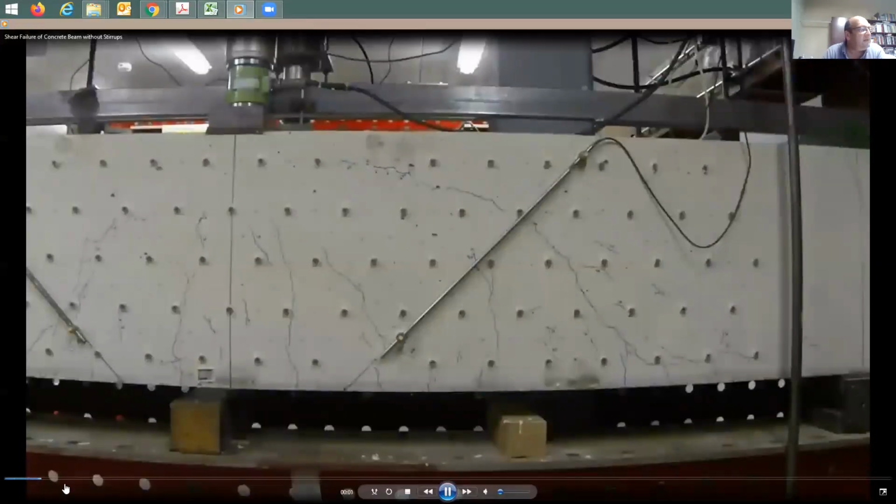Let me show this testing here. This is testing for shear. Now, in this case, the beam is very strong in moment, which means we put lots of reinforcing, right? So we know that the applied moment is going to be less than the capacity moment. Look what happened. But here we didn't put any ties. I guess we're supposed to put ties here, right? To resist the shear. Look what happened.